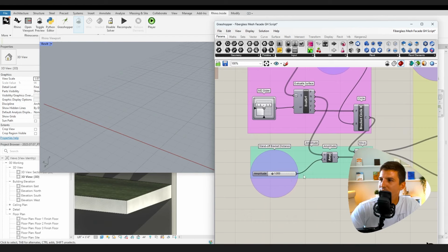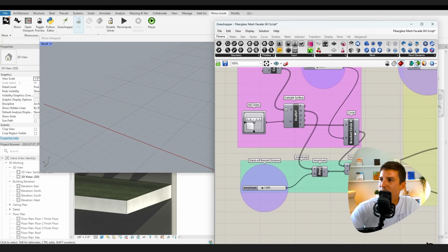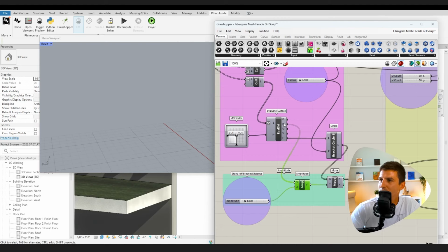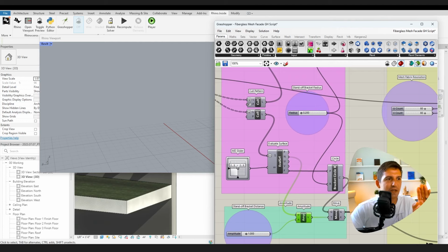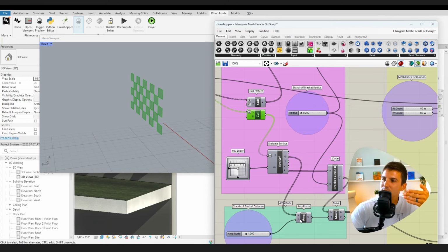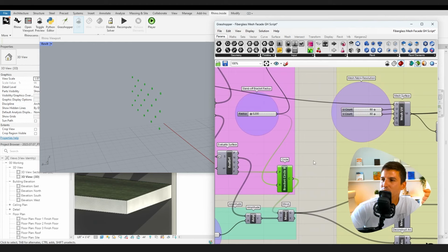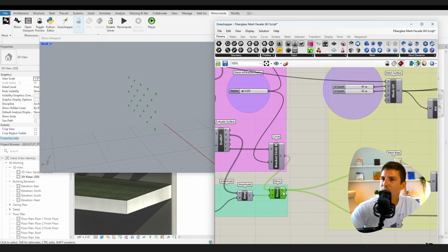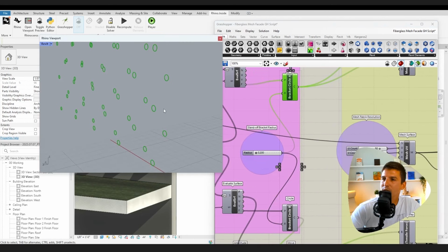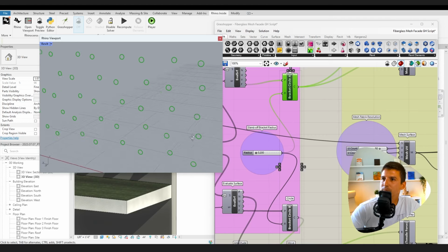And then we have the standoff bracket distance for that second circle. We can take the normal as well. That's the normal vector, the front face on that plane that was in the cull pattern. We can send the normal vector into the direction that we want to send our circle, and the amplitude, the force of that direction that we want to send our circle out from. We can use the Move component, taking the geometry from the circles that came on the center of those surfaces, and we can move them out. We can see that now we've created these alternating patterns of circles.